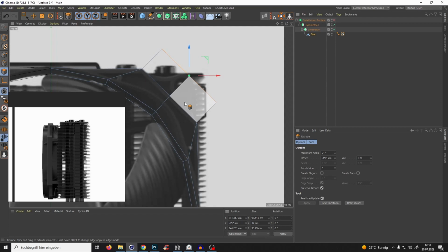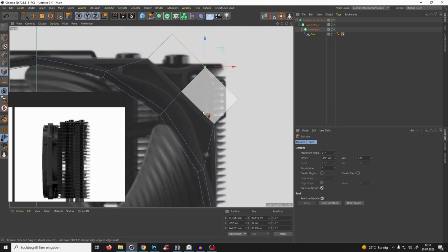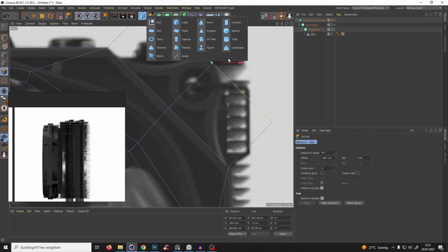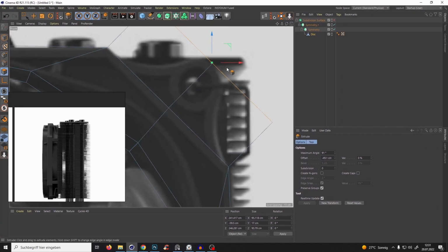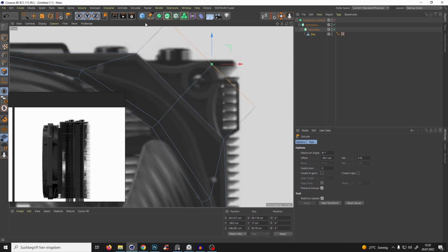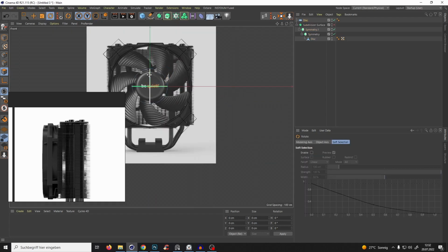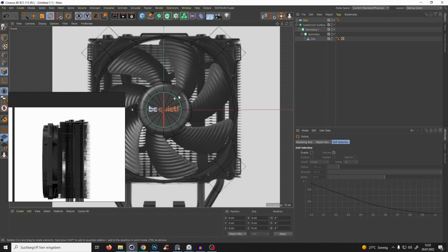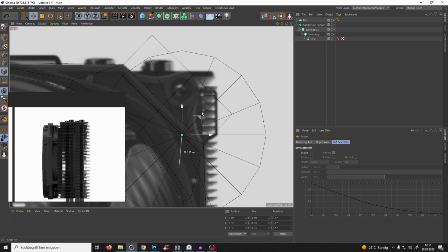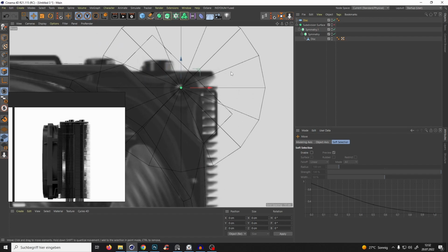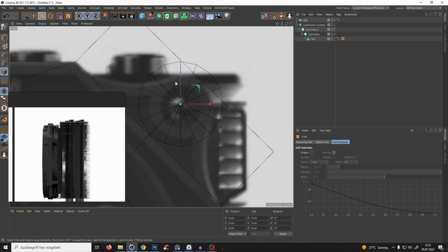Yeah, let's go to the front view and see how we can create the circular shape. For that I use a trick. I create a disk and use this disk as a reference to bring those points to the place. So when we make subdivision, it will create a circular shape. So yeah, disk, rotated to 90 degrees so it looks at us, and we bring this disk to the place of the outer circle frame, kind of. So we just have something like that. How long? 11 minutes.